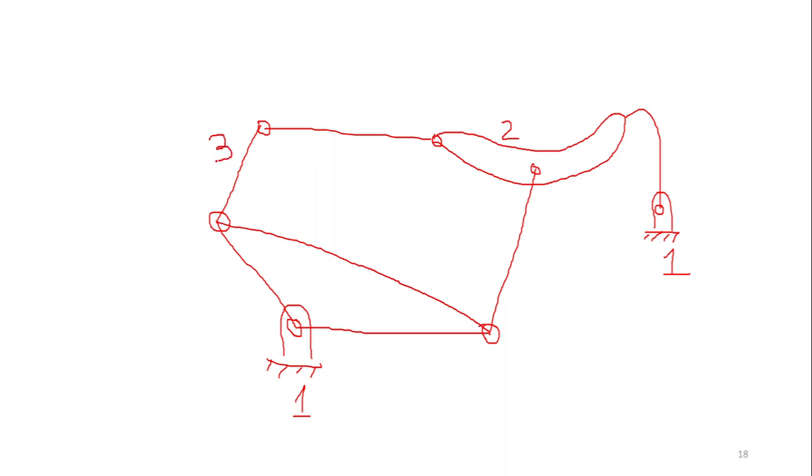Next, three, we have one ternary link here, that is link 4, and one more link here, 5. So the number of links here are 5. Okay. Now we'll denote the joints. So I have a hinge joint here, A, which has 1 degree of freedom.